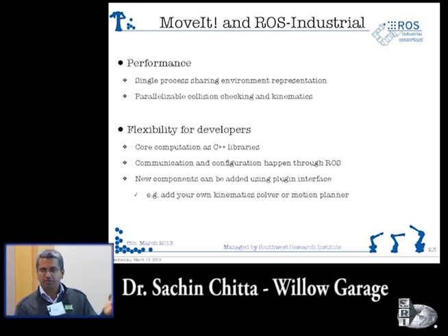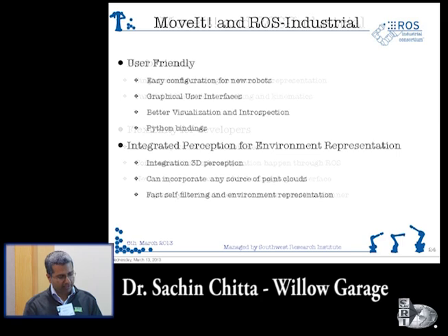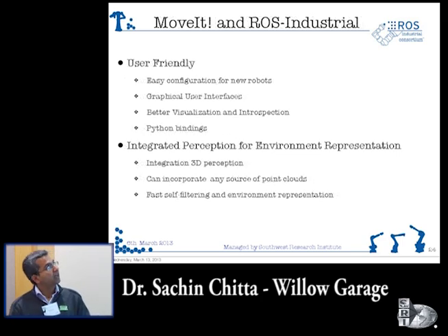The flexibility is also in adding new components. So for example, if you have, say for the ARM, a nice fast IK solver, the current one that we're showing you is basically something that's built to work inside the box. It's a numerical solver that will work with almost any robot that you can build up. But if you had your own, you can easily wrap it up and incorporate it into MoveIt.